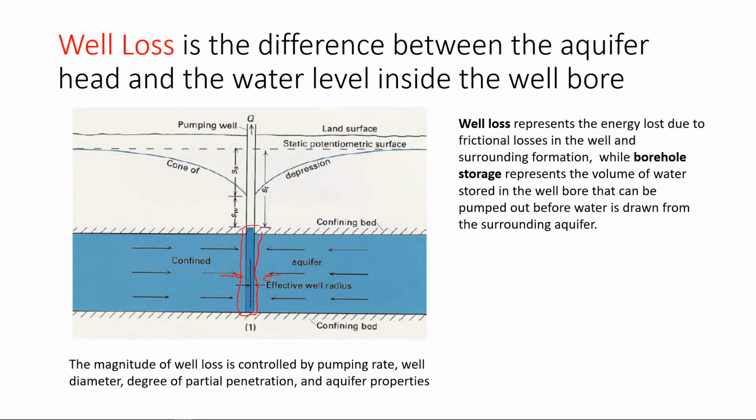So you have water that is here, borehole storage, and you pump this water out before you start withdrawing water from your aquifer. Yeah. So when you conduct your pumping test, you need to make sure that the data you're collecting is not based on borehole storage, but that you're actually drawing it from the surrounding aquifer.